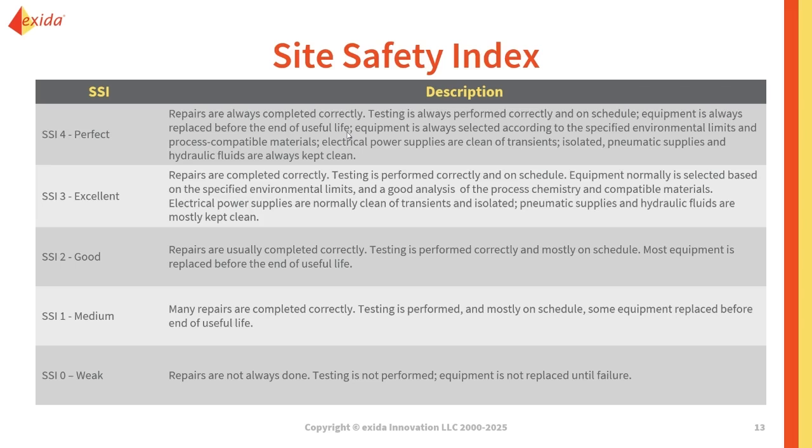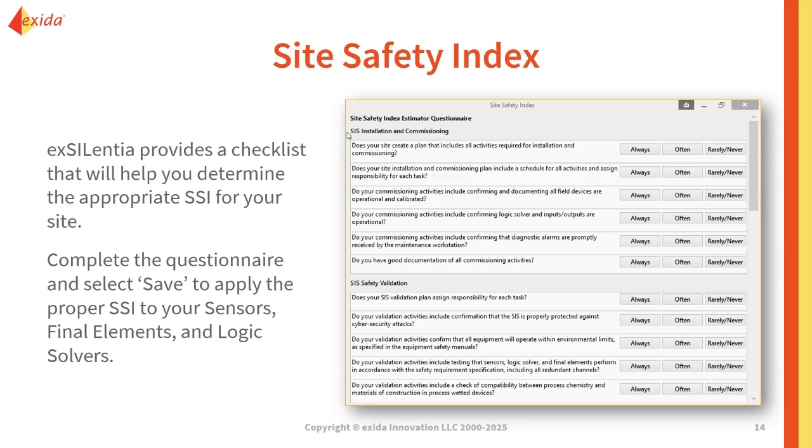This is going to put a bit of a factor on your repair rate and your Markov model for your calculation. And so it basically gives a way for you to consider exactly how your on-site practices impact your exSILentia results. If you're not sure what your on-site practices are, we do have a Site Safety Index Estimator questionnaire.